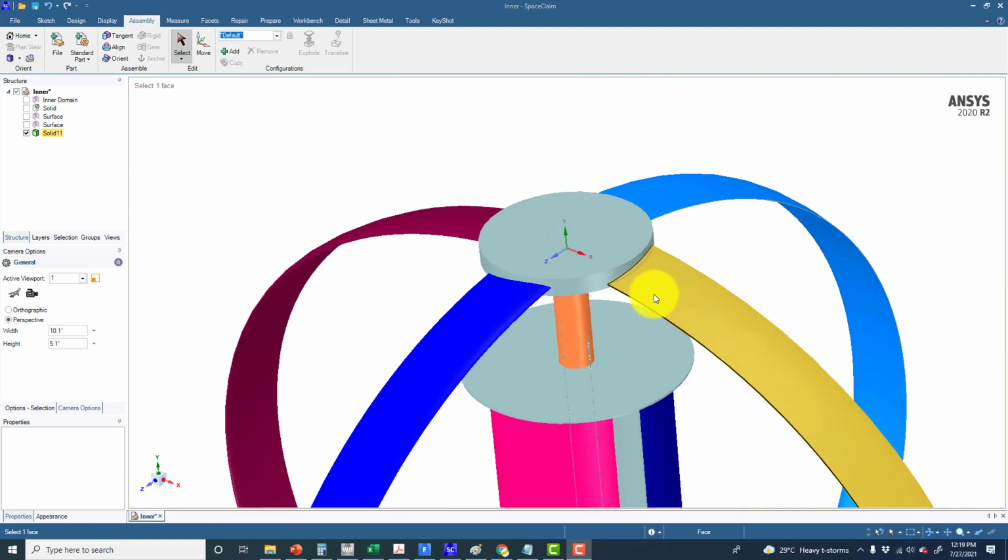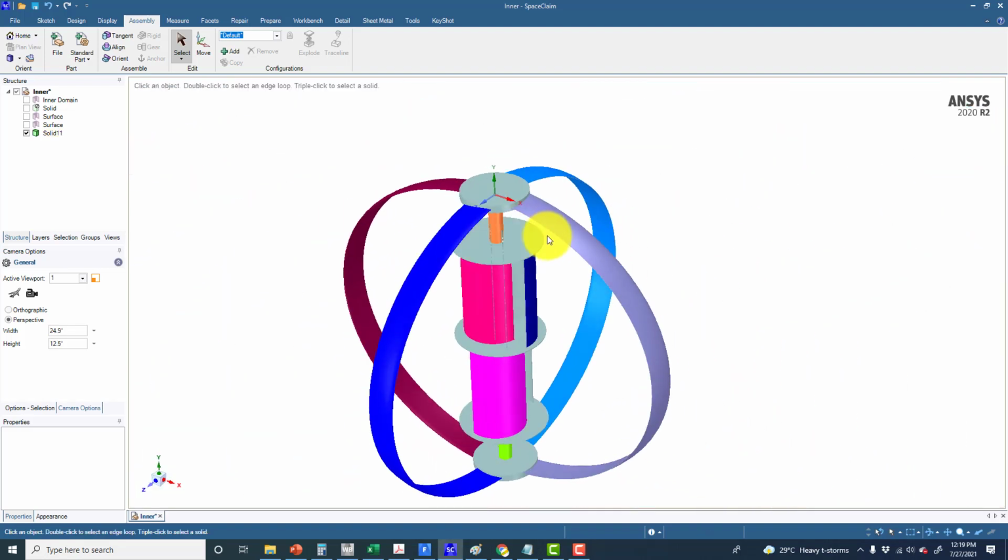As we are going through the geometry creation and remedies for the problems we are facing in the modeling. So after so many videos and so many steps, now we have the correct geometry. The next step in the CFD is to create the domain. Because it's external flow, the domain is around the body, and for any internal flow that will be the domain inside that geometry.